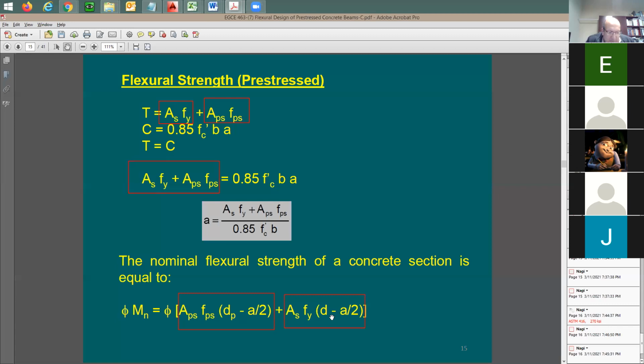In post-tension, what do you do? You put conventional rebars, right? And then you pour the concrete. And then, of course, you put the strands in there, but you don't apply the tension force to it. And then, in some cases, you can strip the form, just take all the formwork and all the shoring out. Now the beam is supported like this. Supported by what? It's going to be supported on itself. And it needs to have some conventional rebars, and there is no post-tension yet. You did not apply any tension to it yet.